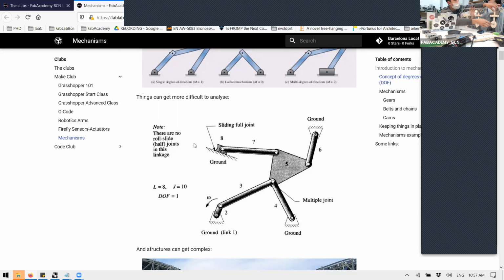or however you want. Can you repeat? So the idea is that you define this profile so that this moves in a non-linear way from up to down, like a certain profile of I go very fast to here, and then very slow, and then very fast. So variable speed, the same as here. You have suddenly small increments, small increments, small increments, until suddenly it reduces, because of the shape of how this body is defined.